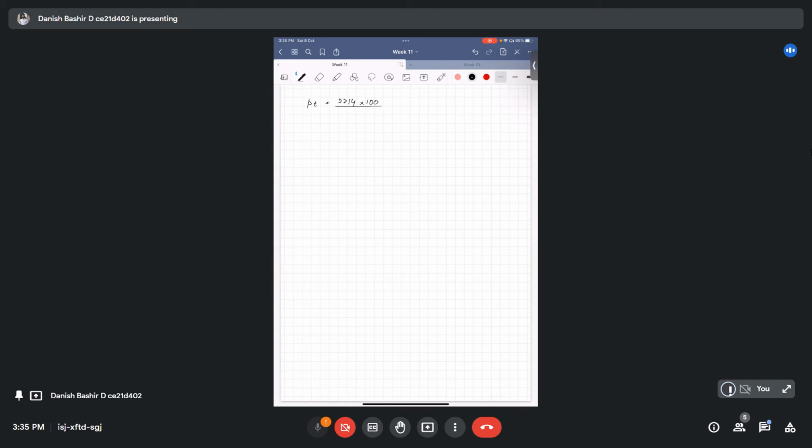B is 350, D is 700. When you calculate, this is 0.904. When you look in the table from the code, under the column FCK equal to 25, you will find that tau C, the shear strength of the concrete, is 0.618.